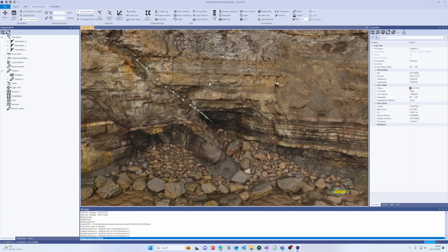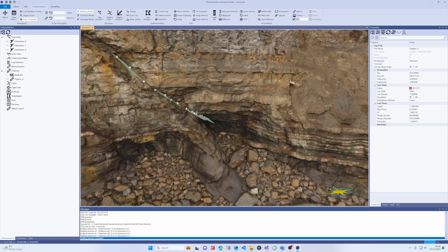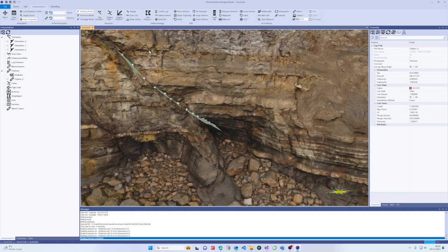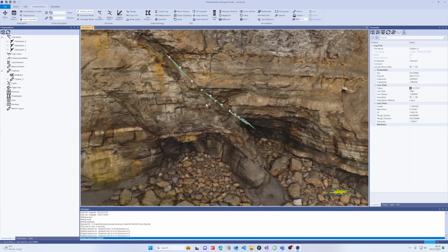This does mean that sometimes when you draw the polylines, the polyline that you end up with is not necessarily good enough to get an orientation from. You can then add a structural measurement that you've taken specifically, or one that you've collected from the field, and update the value of the polyline that you've just drawn.